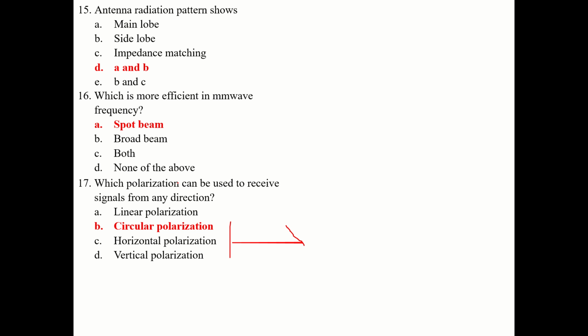That's why most satellite communication and radio receiver stations use a circularly polarized antenna. When the signal comes from the satellite transponder to the ground station, it passes through the ionosphere, troposphere, and stratosphere, many layers, so a polarization twist will happen because of diffraction.